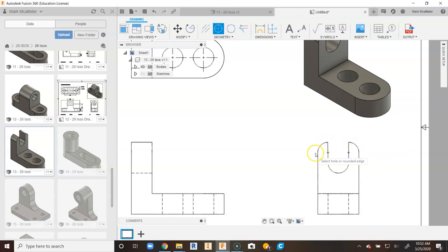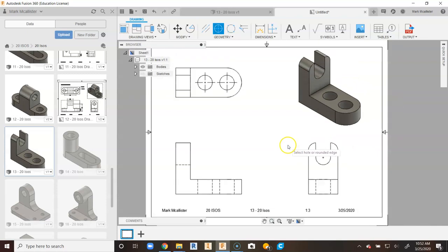It kind of tells us where the center of that fillet is that we did in a previous video in making the part. We need to go up to center line bisector. We need to place for ourselves a center line between here and here, because we know we have holes up here at the top. We have to show where the center line is. Now you could get into an interesting question that since this is an arc over here, should we place a center line up here between here and here? And I'm going to say yes.